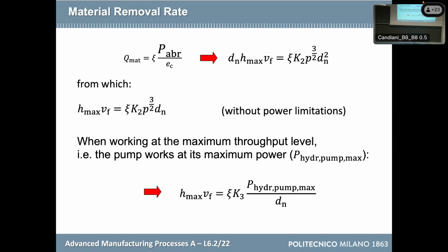And yesterday we have seen that the best way is when you are on the knee of the characteristic curve of the pump. So we want to maximize the diameter of the orifice. So also there, it is not a variable anymore. You have to fix it at 0.30 or so, 33, depends on the pump. But again, it is not a variable anymore. So for this reason, I'm removing it from this equation.